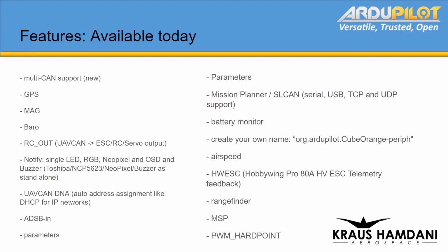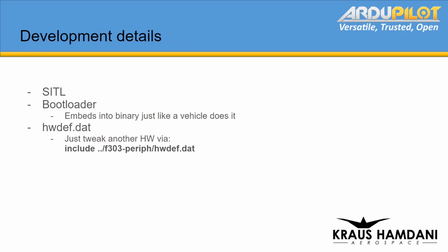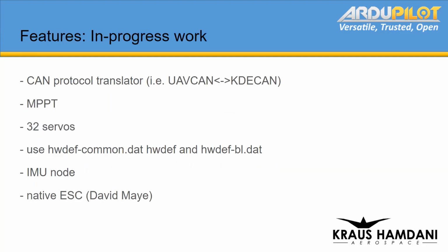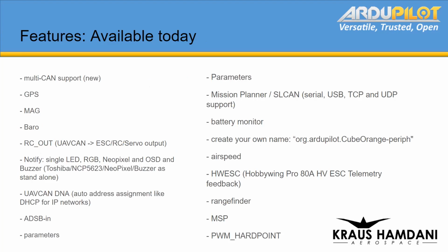And I'm not sure going the MAVLink route, encapsulating MAVLink, is necessarily the best idea, because we end up with a fairly complex parser of that MAVLink, and the original OSDs that were based around MAVLink weren't as good as our current OSD. They didn't provide the information in the same level of detail, and they were a lot less efficient.